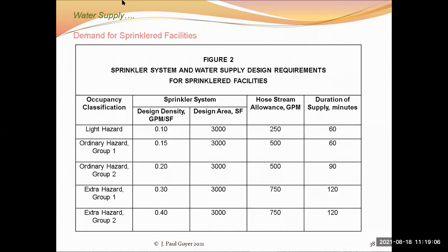let's see, Jeffrey says, plastic piping trend for domestic water supply, implication for firefighting. Well, you would not use plastic pipe for a fire sprinkler riser, something like that, or for the piping for an automatic sprinkler system. I don't sit here reading these codes every time they come out with a new edition, but I'm awfully positive that plastic piping would not be allowed for the water sprinkler system in a building. I don't know if that answered the question very well, but anyway,